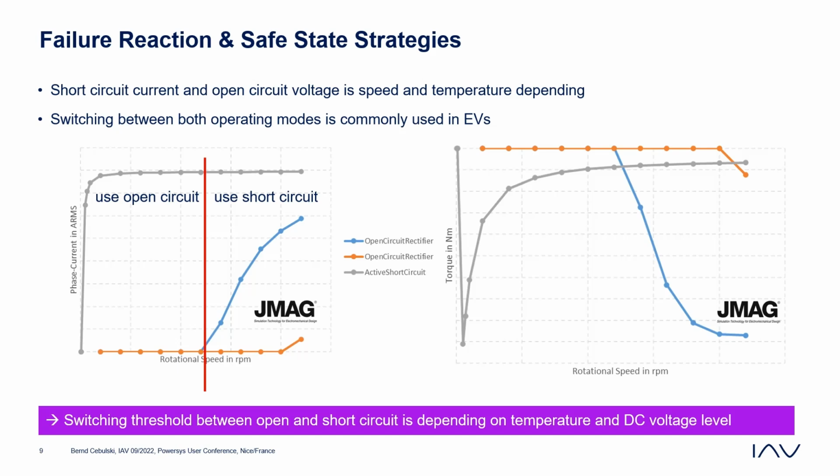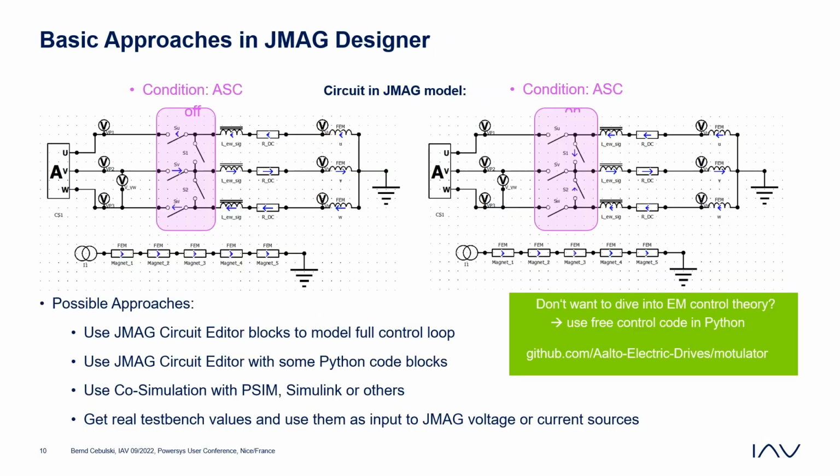The torque shouldn't lead to any dangerous situation on the car. You might drive on slippery roads, some icy road. So anything, the uncontrolled torque is dangerous. And the current, as I said before, is heating up the machine and maybe also endangering the inverter. So every one of these values needs to be known, needs to be simulated. How do we approach that with JMAC?